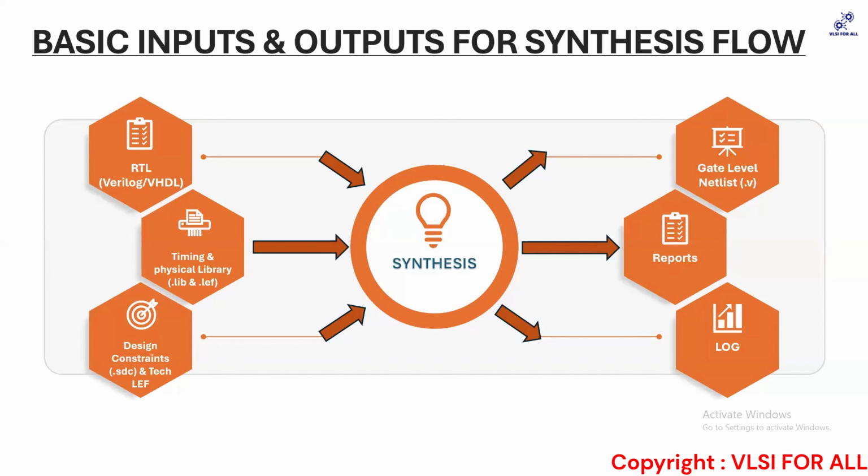It can be something like the way your flow has been designed. It is like a zip version of all the outputs which are being dumped by synthesis and kept at one place. Yes, it can be like this, because you are saying it has constraints, it has netlist, it has everything. So it might be a flow that has been designed to dump it in that manner. Okay, I'll go through it, check if there is something called .ddc, and get back to you in the next lecture.